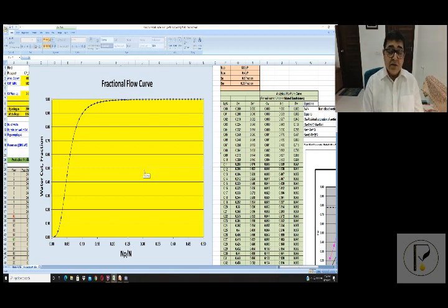Now, if we go into, let's say, the heavy oil regime of 500 centipoise, the viscosity, the fractional flow curve shifts to the left. That means at 90% breakthrough, we get a very low recovery of around 7 to 10%. This is not a rosy picture at all. So what happens? From day one, that's what I said, some of the EOR processes have come out of the tertiary EOR bank. They have come right at the primary stage.